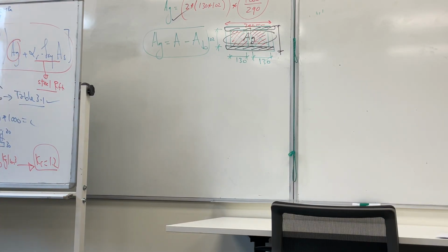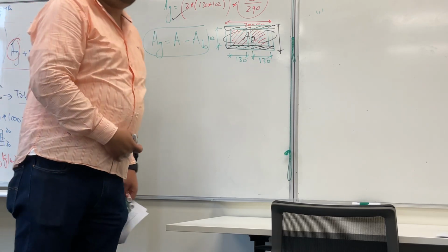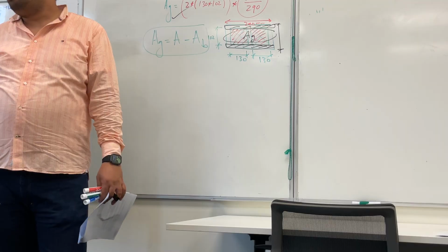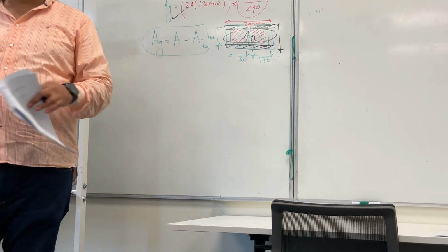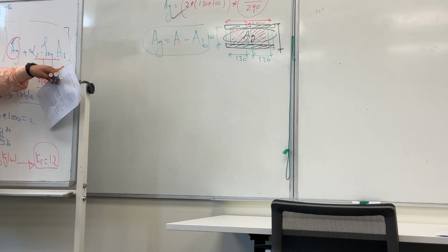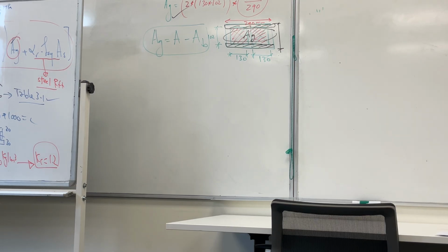So what is the next step? If we know Kc and fcg and Ag, we finalize this part. This part we don't know, so we need to assume. You can assume and check, or calculate it by reverse. You can reverse calculate the required area. We know fd, and we know phi and Ks and all of that, so we can find As. Or we assume 4 bars or whatever and then check. I think it's better to reverse calculate.